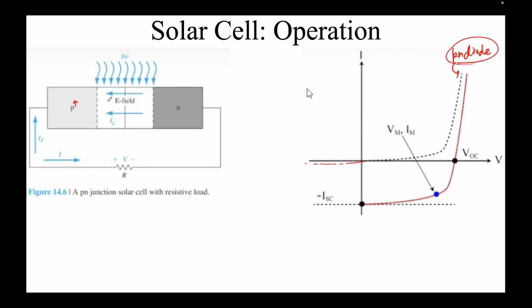So, as I told you, the continuity equation that I had briefly alluded to in my opening remarks. So what we have here is the excess, and we'll write that expression: del square delta p over del x square, this comes from diffusion, right, minus delta p, the excess holes, over tau, their lifetime in which they recombine, plus the optical generation rate.